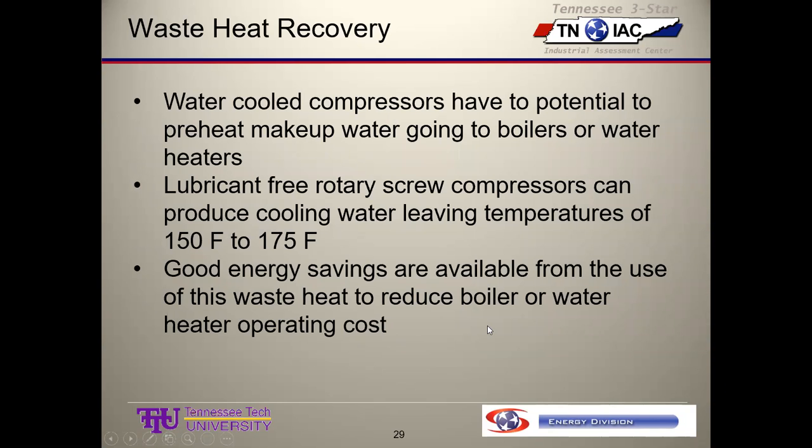Okay. More comments on waste heat recovery from the compressors. Water-cooled compressors have the potential to preheat makeup water going into boilers or water heaters. Bridgestone over in North Carolina had a big utility room, a big mechanical room, and they had boilers and air compressors all in close proximity. And they had some big air compressors, and so they were water cooled.